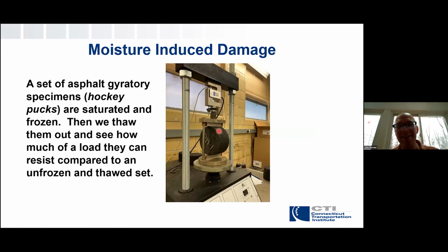This is known as an indirect tensile configuration. And the reason we'll do this, right, you might think similarly to concrete, well, why don't we just put it on its top and crush it that way? The reason being is when you do what's known as a uniaxial compression, I know I'm throwing a lot of engineering terms here, but hey, what the heck, it's Friday. When you crush a concrete cylinder, which looks more like this, you're only testing for compression.